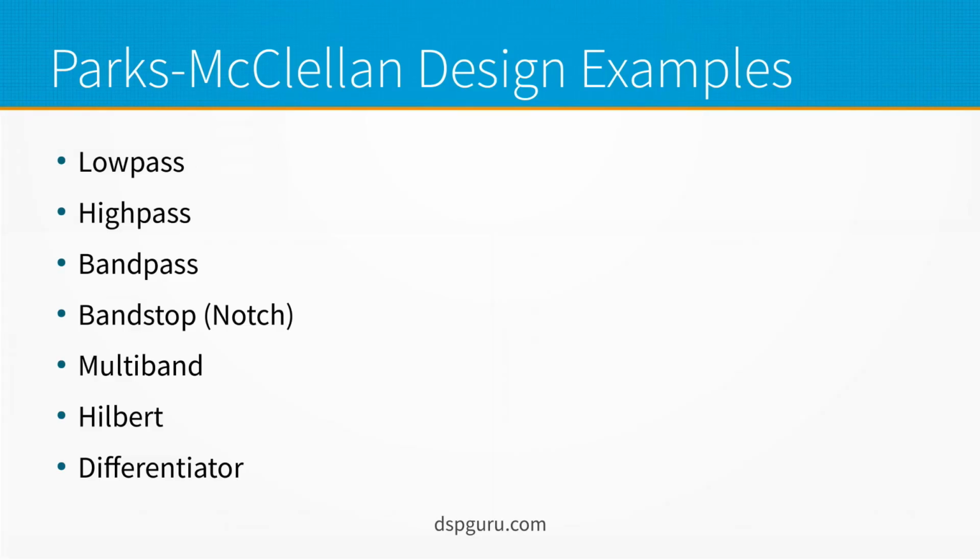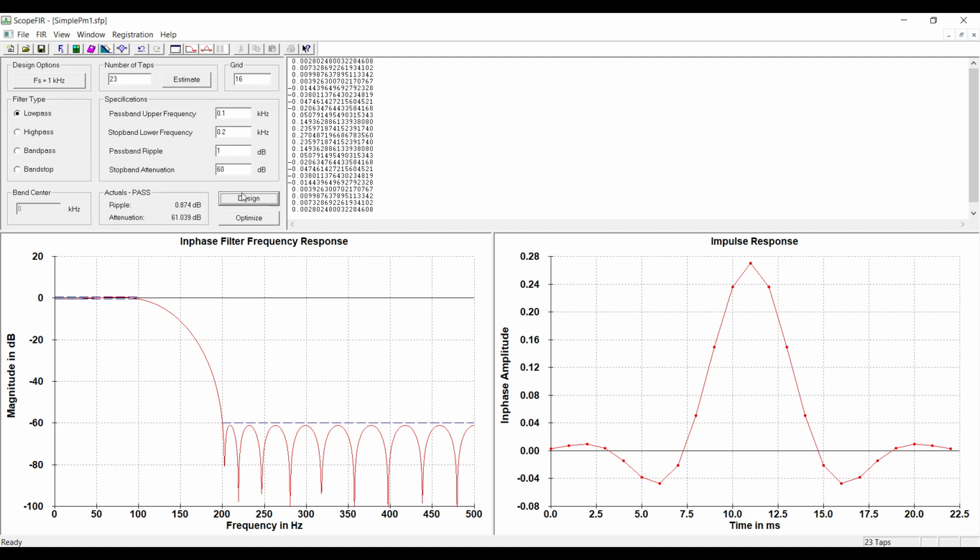So next I'm going to do an analogous design that's a high-pass filter, uses all of the exact same specifications except for the band edges between stop band and pass band are interchanged. And as I hit this high-pass button, you'll see that these automatically get updated to kind of reuse our parameters for a high-pass situation.